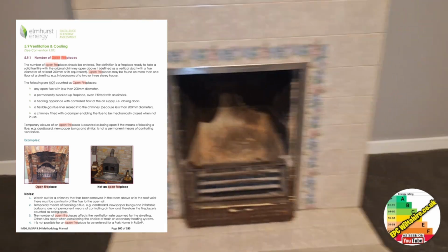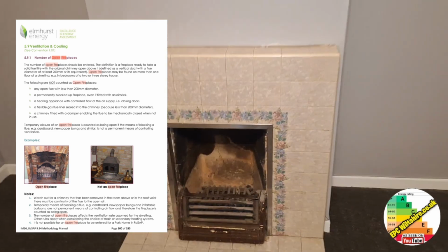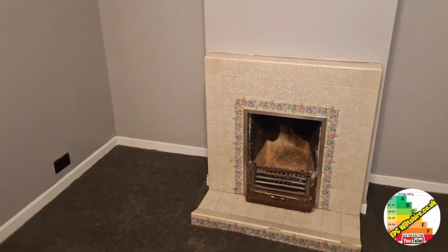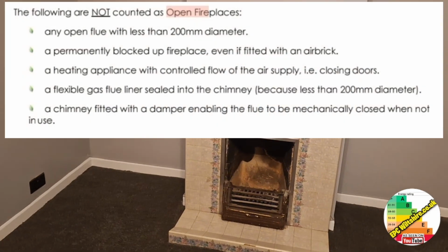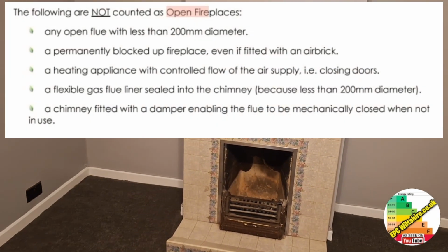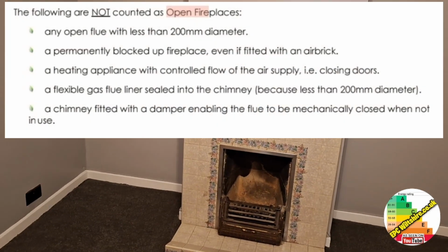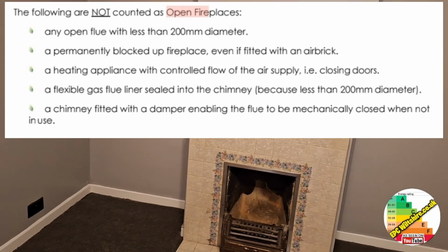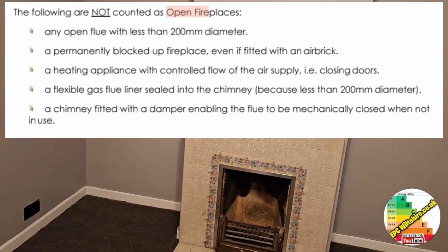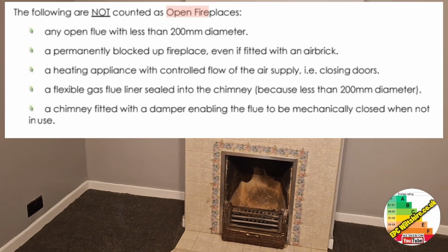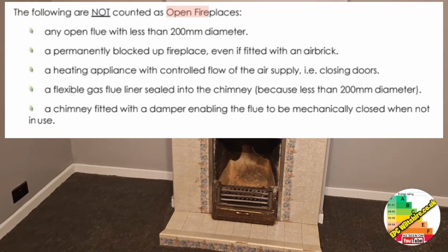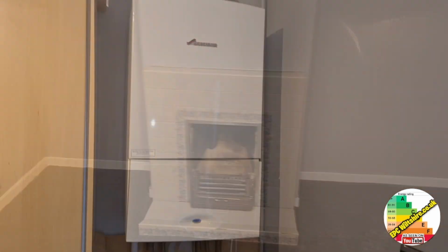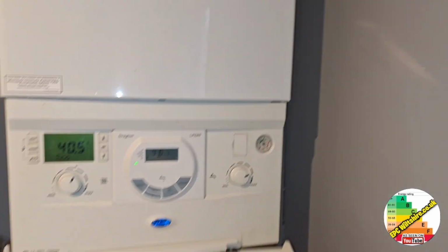Now in the manual, an open fire isn't counted as an open fire if the opening is less than 200. Now we have a 400mm opening on the width, so I'm saying it does count. But the depth was only 111mm. So if it was all less than 200mm width and depth, or diameter, then it wouldn't count as an open fire. And the boiler here is a Worcester